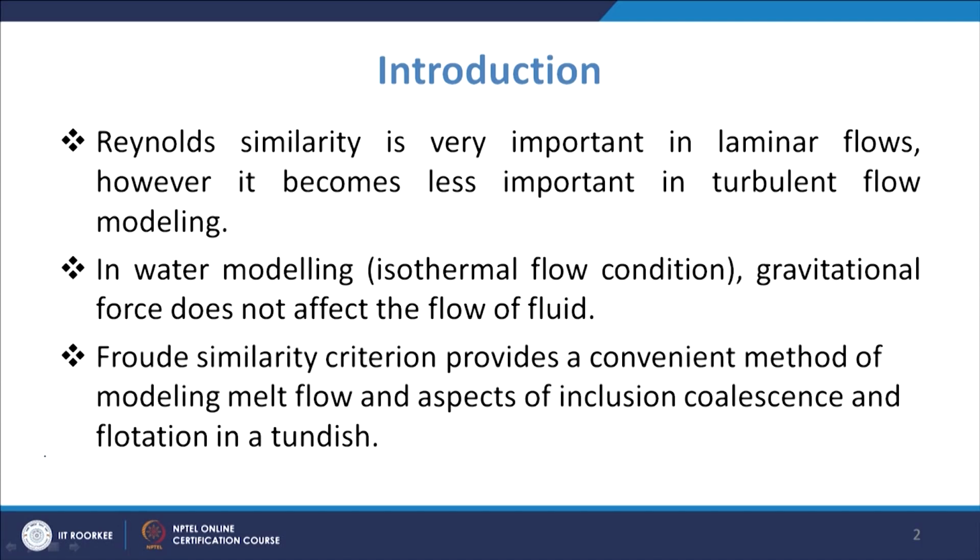So, the gravitational force will not be affecting the flow field. We have seen that if you try to maintain both similarities, then you have to keep the model and prototype size the same. So, that is what we have studied earlier.